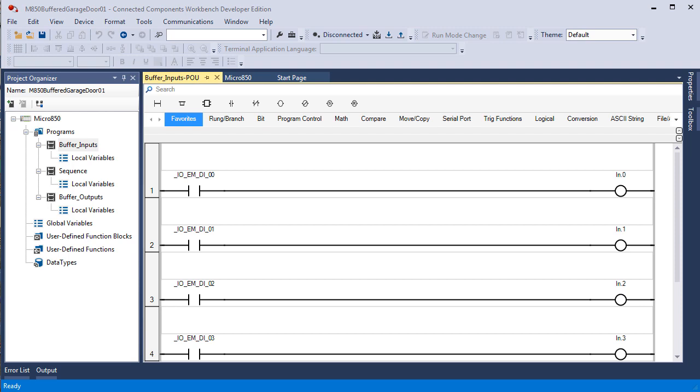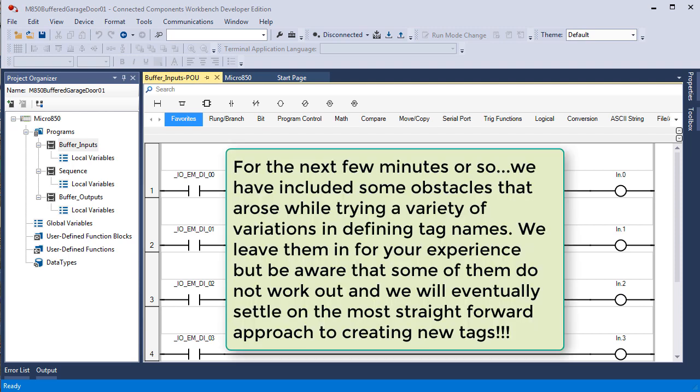With memory being as inexpensive as it is, that's the trend. In ControlLogix and CompactLogix, the native data type is DINT, double integers. So if you create a Boolean, a single Boolean, you just used one bit out of 32 and the other 31 are hanging in the breeze and they will not be used. If you follow along what we did in the manual, I'm going to try it in a different way.